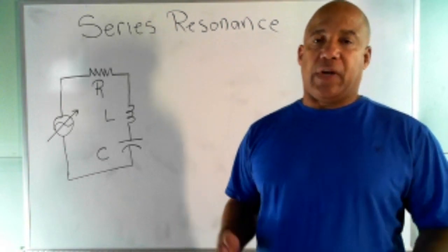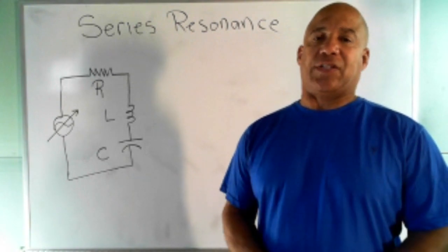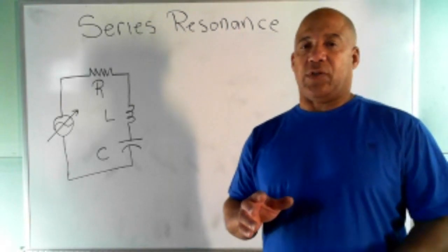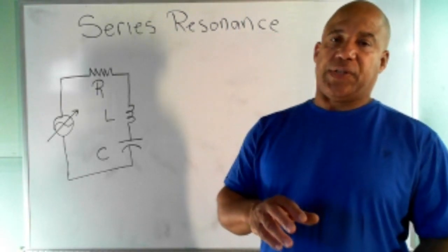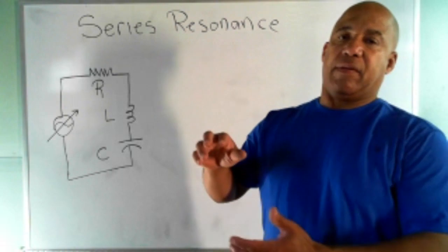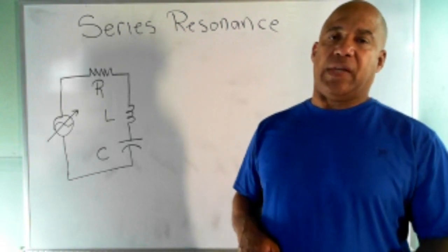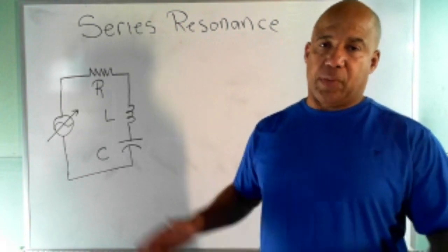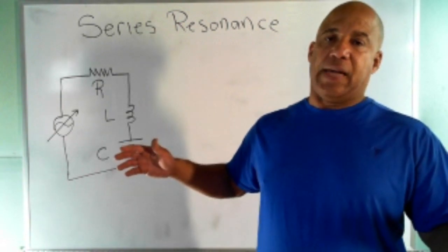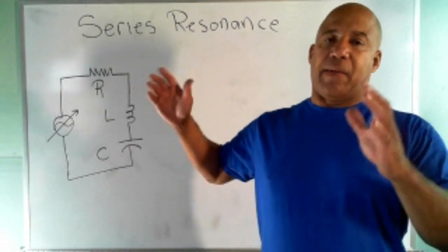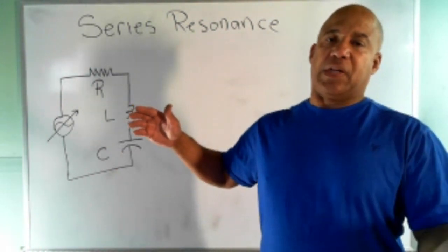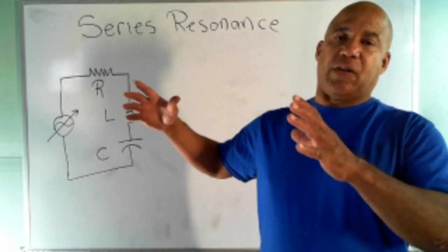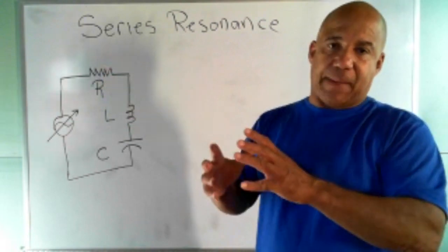But so do circuits. I showed you how you can put energy into a capacitor, and if I have an ideal capacitor, it'll hold that energy forever. But I hooked it to a switch and an inductor, so that when the switch is closed, the capacitor discharges through the inductor and builds up the magnetic field around the inductor. As long as current is flowing from the capacitor to the inductor, that magnetic field is sustained. But when the capacitor has discharged, there's no more current to maintain the magnetic field, and it starts to collapse. While it's collapsing, you have Faraday's law.